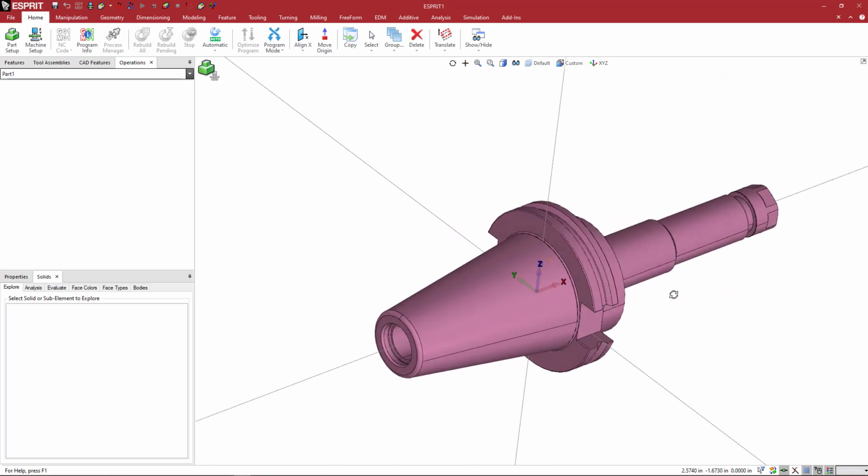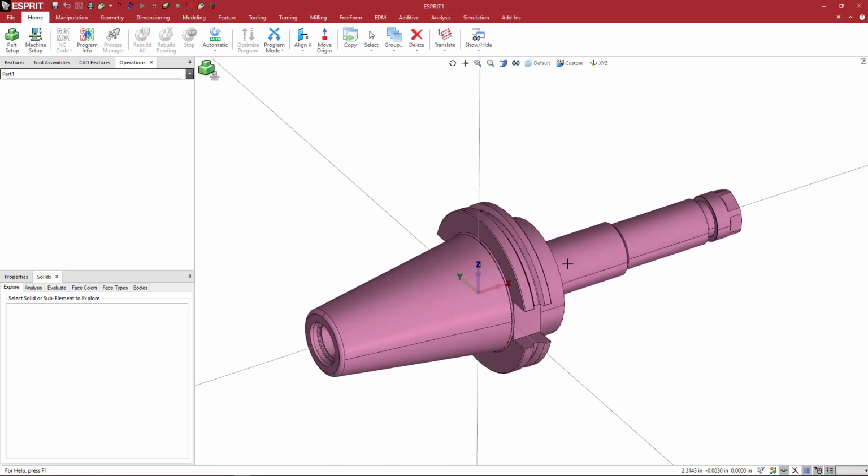And if we look at this, what we need to do is basically rotate this portion down so that it is aligned up and down with the z-axis. So we need to rotate about the y-axis a positive 90 degrees. And how do we know this is positive? If we put our right hand, our thumb, in line with the y-axis on the screen and we curl our fingers, that's the right hand rule. That's going to show us that we need to move in a positive 90-degree rotation.